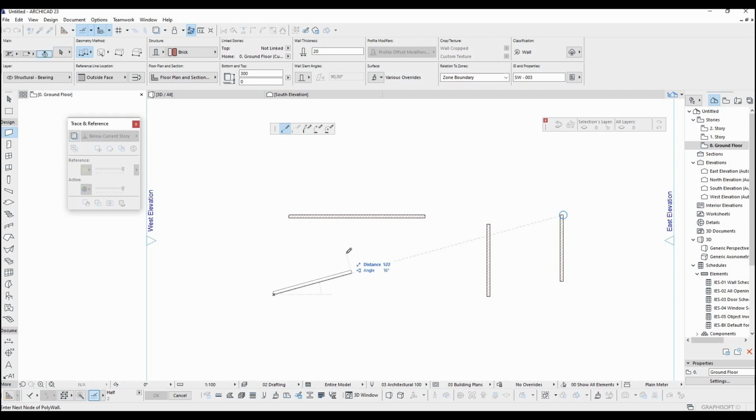It's also locking onto prominent angles like 45 or 90 degrees. There is no need to press the Shift, but if you do that, you can also move with that angle and continue to another point and align.